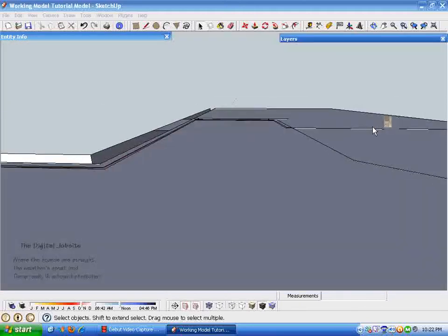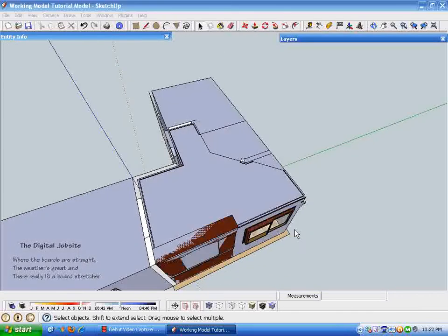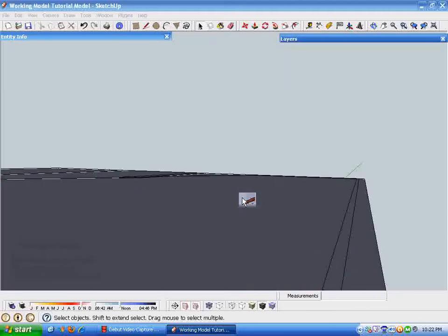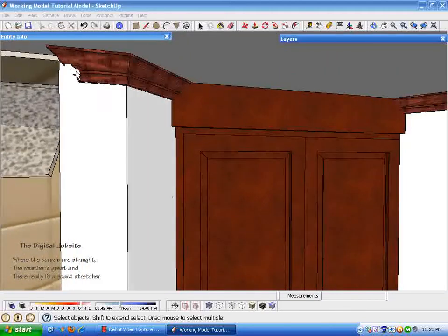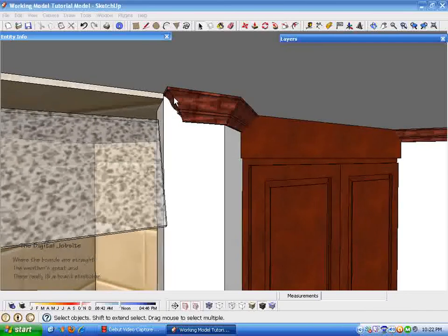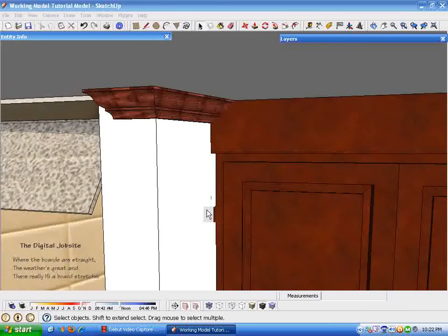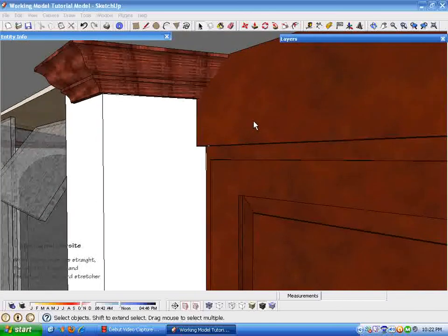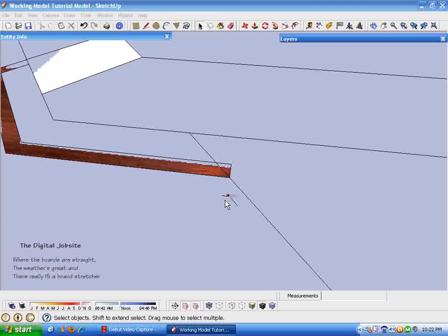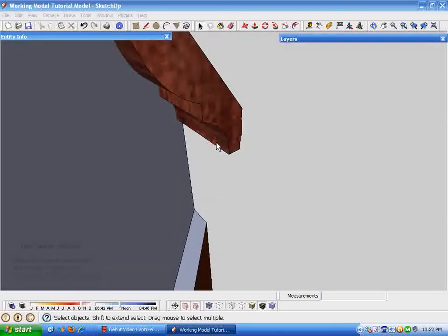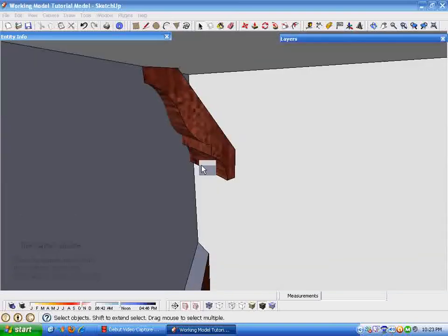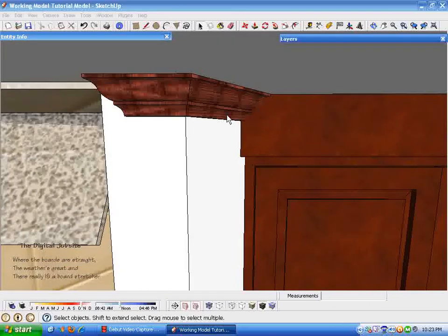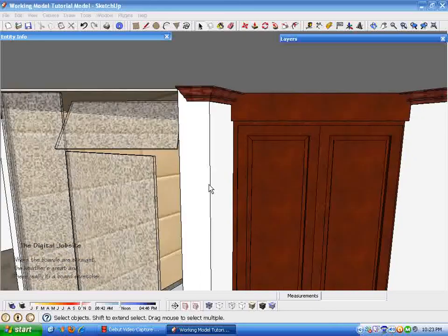And it's simple to draw the geometry on the ceiling. Just move it out some arbitrary distance, work on it, and then put it back that arbitrary distance, rather than trying to work around your model and pick out lines. Put the lines in here using guidelines and everything takes forever. Another thing I did to cheat here was I just ran this crown molding in to the fascia on this cabinet, or that soffit. You can see how if we go down inside the cabinet here, the crown molding just sticks inside, but that's irrelevant. You get the idea from looking at the outside, and it's not really necessary to go in and trim that geometry. If it was, you could.